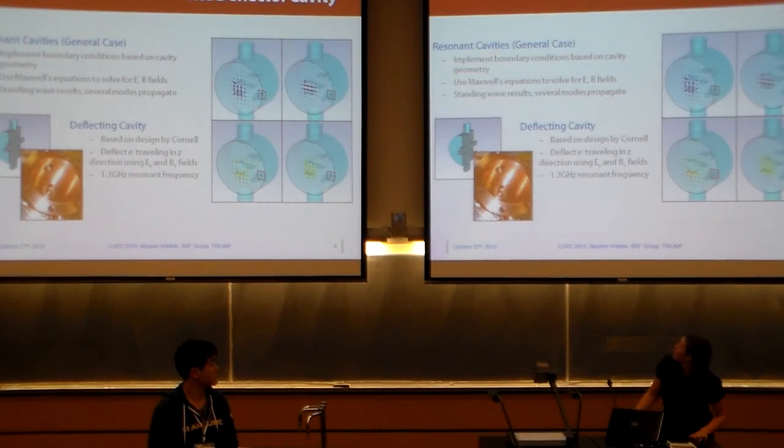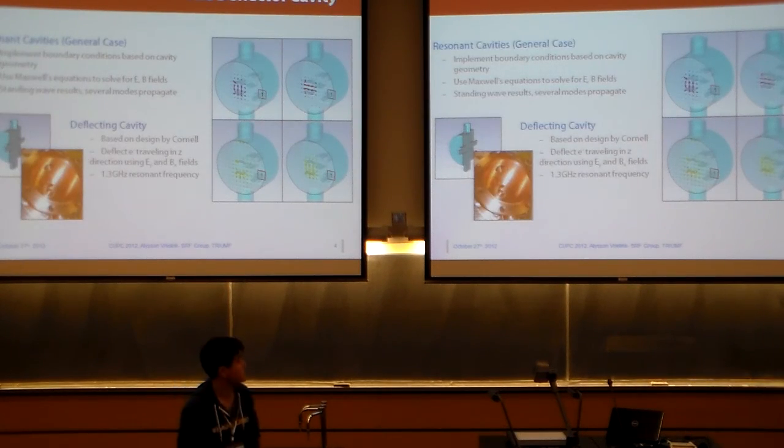let's go back to here. You can see that this cavity has these nose cones sticking out. And if you notice the nose cones, that's where the fields are the strongest. These nose cones also affect the resonant frequency. And when I said we wanted to drive it on that frequency, we had to tune our cavity once it was built. And this is an unexpected thing that you have to do. You build it, and then you use a network analyzer to find out the resonant frequency.